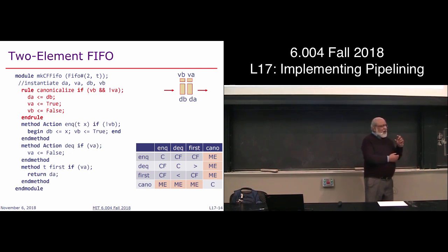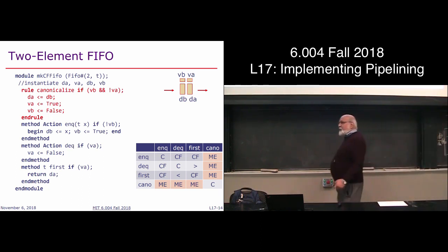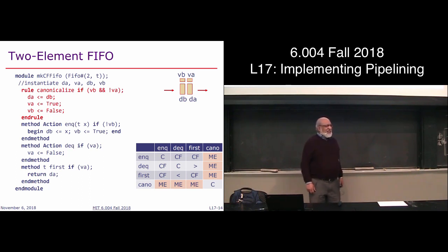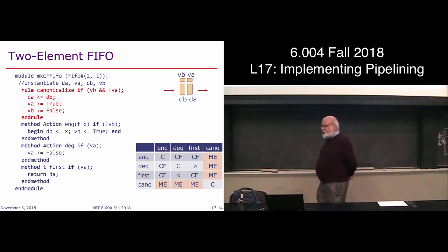So if you had only one port, you can supply an address for either the first read or the second read. So parameter-less read methods are conflict-free. If your read method has a parameter, then again there is a conflict. It's like a port conflict. You just can't use the port, right? Because there is already something else going on. But it's an easy fix. If you want, you can create a new port. Then you just go and create another read port inside. In fact, the Bluespec compiler can almost do it automatically.